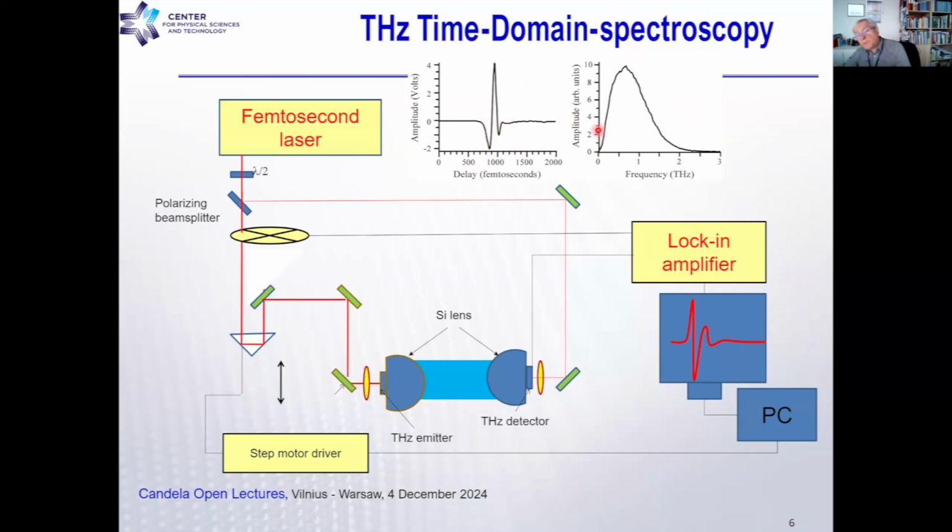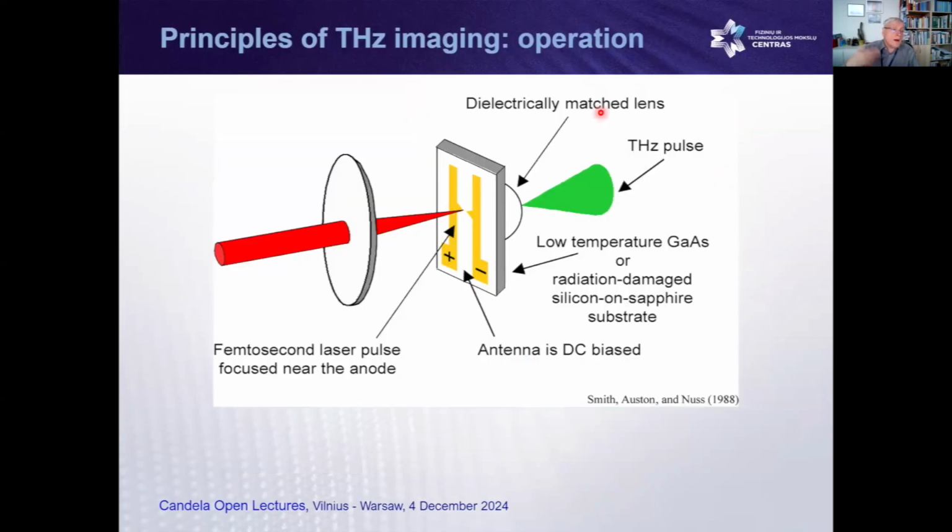If you go to the Fourier transform, the shorter the pulse, the broader the spectrum, and then we can extend the scale. Currently we can go up to 5 terahertz using the antennas approach, and it's pretty good for spectroscopy. What is important here is the so-called transient and the fast Fourier transform, and here is a direct experiment. In fact, the terahertz spectrum just appears from mathematics, and this can be applied for further analysis.